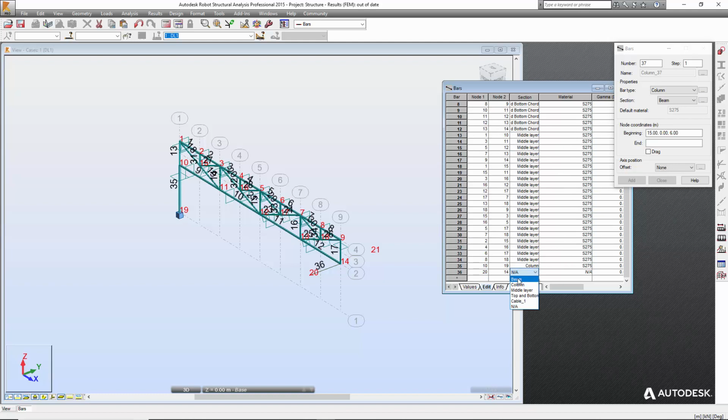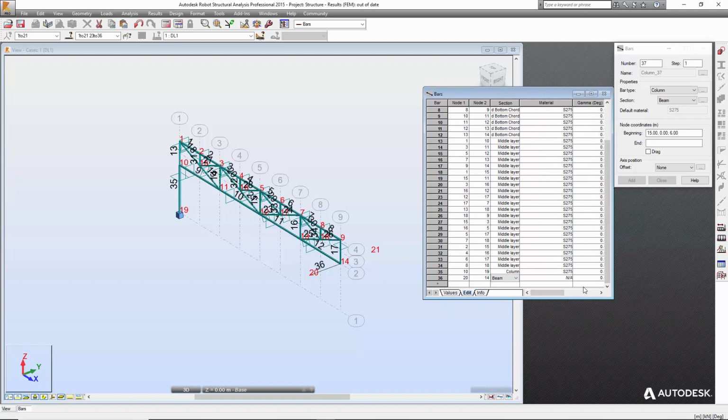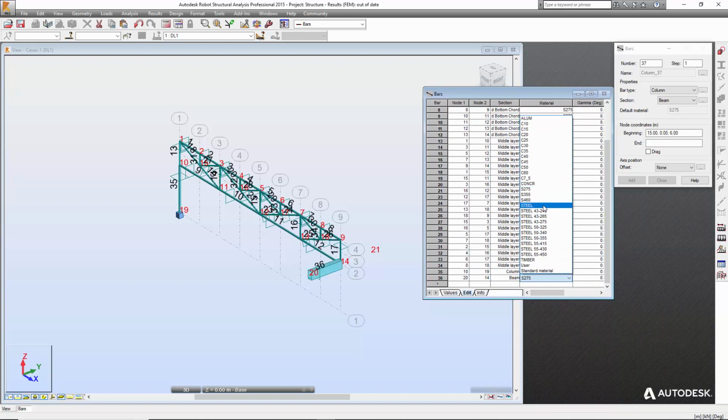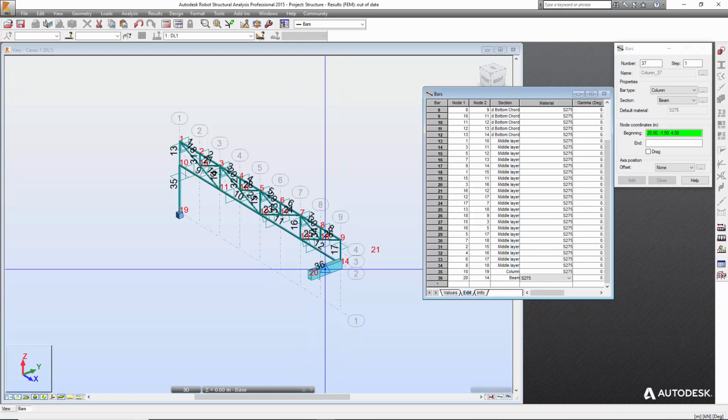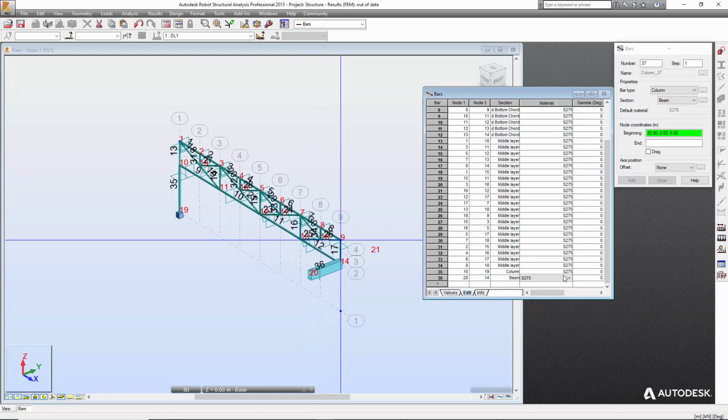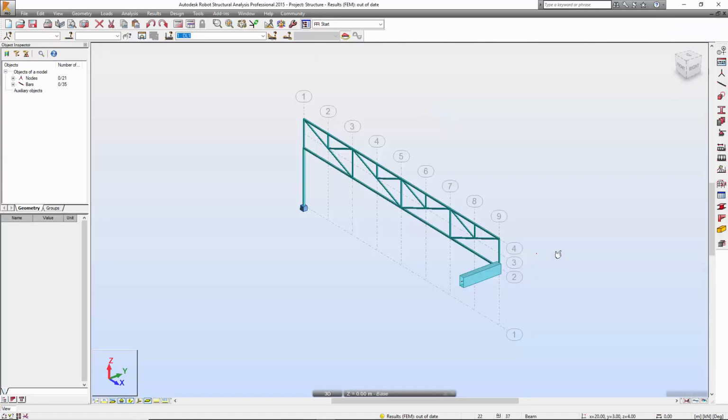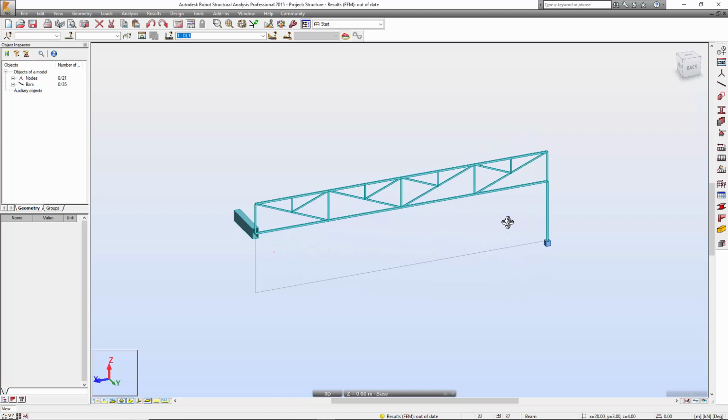So then you can select the bin. You see, once you change it to bin and then you close, you also need to make sure this one is going to be the steel or S275. It will be the same as the steel bin. Once you choose this S275 or steel, because the Young's modulus should be the same, and before you close this one, you see this bin has been changed already in here, right? So you can use this way to do that. Let's come back to start, and then you see this bin has been created. One section of it is created already.